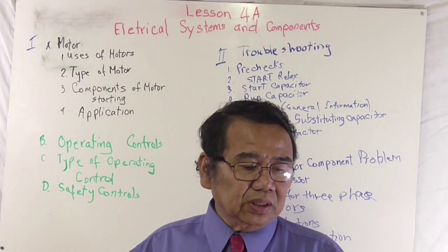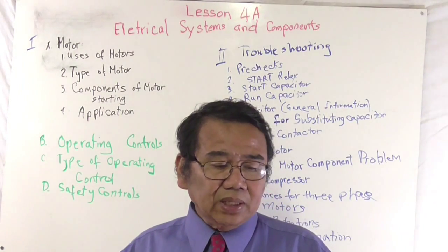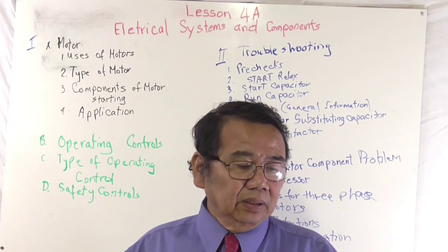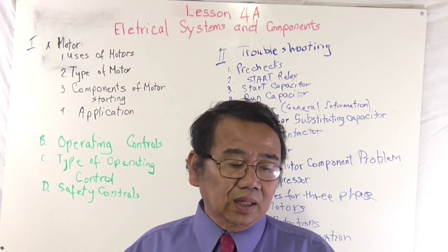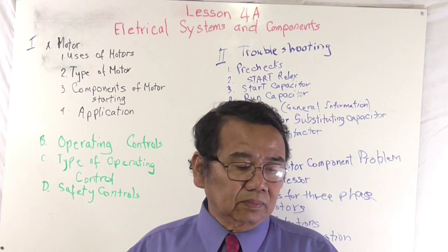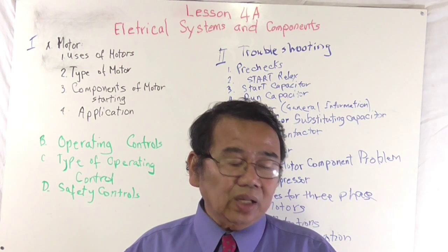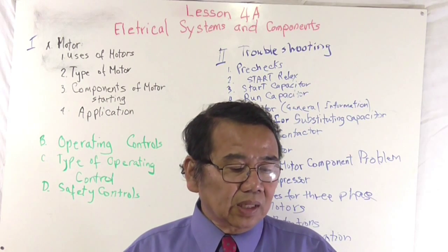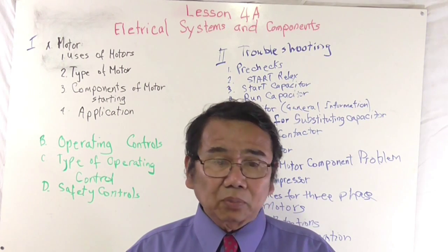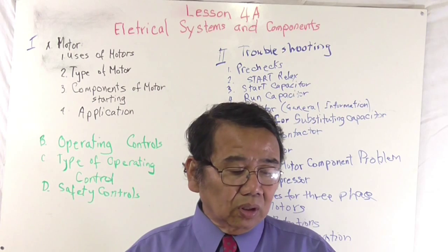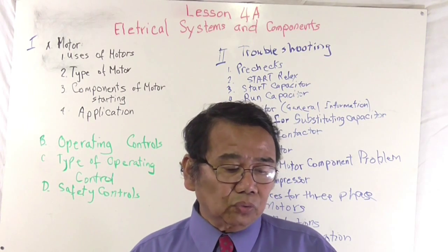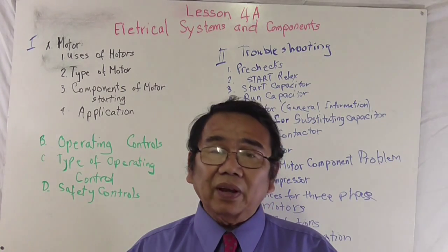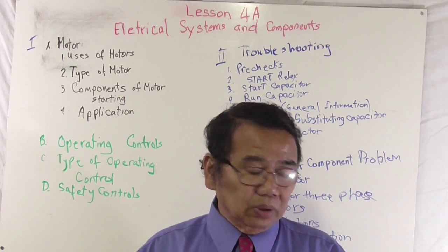Pre-checks. There should be 5 basic steps done before beginning electrical troubleshooting. They are: check the air filter, check the thermostat, check for line high voltage, check for controls, usually 24 volts, and get the fans working first.